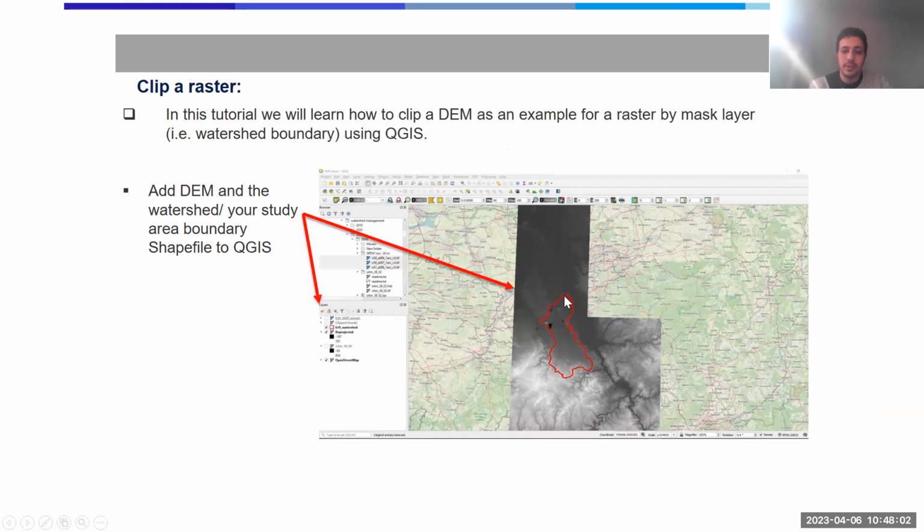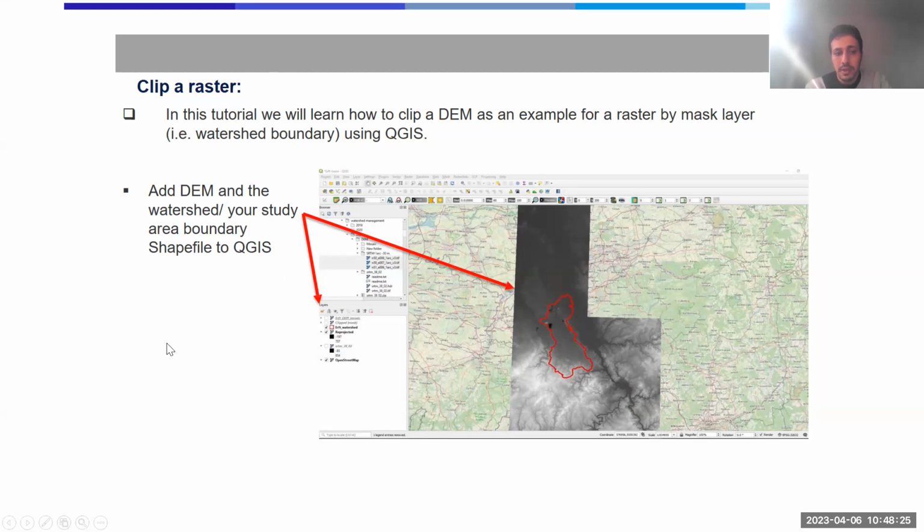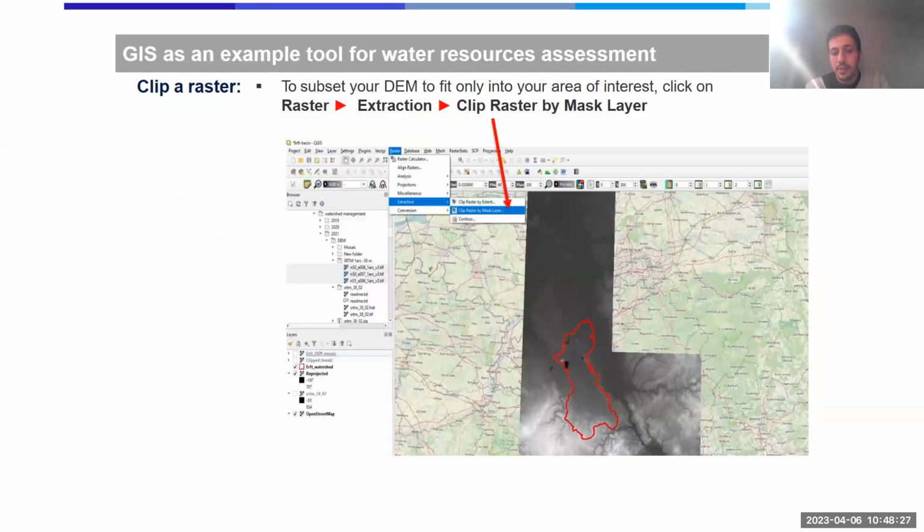And these borders are not raster, as we also said, it's a vector, which just represents the boundaries of the basin. I just want the data inside my basin, because I have a legend here and I will be confused about where it is. So first we need to clip the raster, and this is a tutorial on how to do it in QGIS.